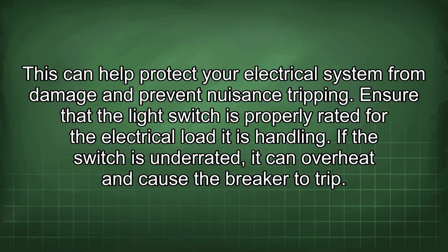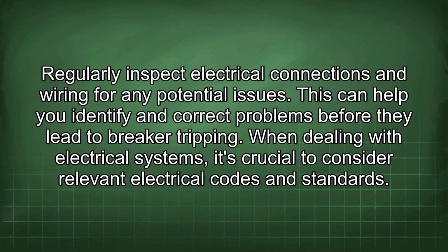Ensure that the light switch is properly rated for the electrical load it is handling. If the switch is underrated, it can overheat and cause the breaker to trip. Regularly inspect electrical connections and wiring for any potential issues. This can help you identify and correct problems before they lead to breaker tripping.